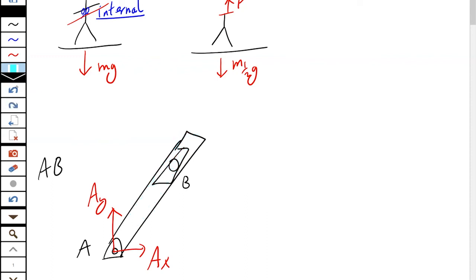The other half of the rule, if it can't move in a certain way, then there is a force reaction. This pin can't go perpendicular to the slot, so that means there is a normal reaction force perpendicular to the slot. In fact, if you look at it, it's just like the beam was between two rollers, just the other way around, drawing it. How do I know it was up and to the left like that? I don't. I just had to choose a direction, so I chose one, and then the math will tell me what the actual answer is.